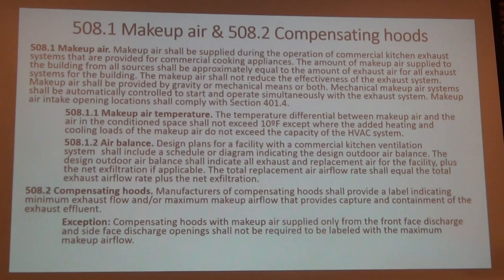Compensating hoods and makeup air temperatures. The temperature for the makeup air has to be within 10 degrees of the room temperature. So not only is it heating, but if the kitchen's air conditioned, it has to be within 10 degrees.